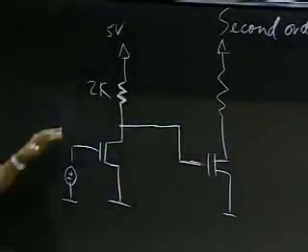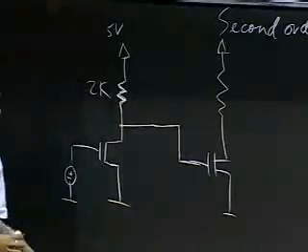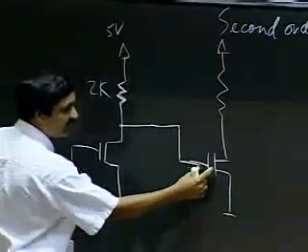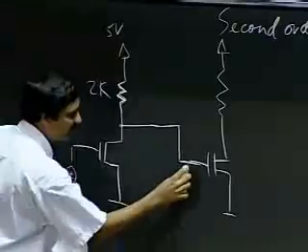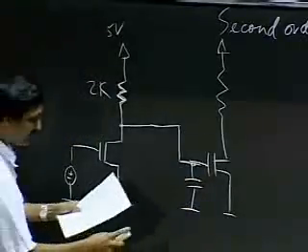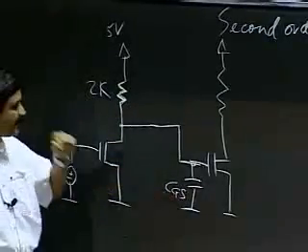And what we saw in the last few lectures was that in this specific example, there was a parasitic capacitor associated with the gate of this MOSFET, and that could be modeled by sticking a capacitor CGS between the gate of the MOSFET and ground.